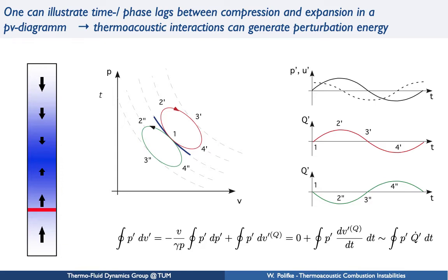And the blue line that you see here would correspond to isentropic compression and expansion that a volume of gas experiences if it is exposed to an acoustic wave. Only an acoustic wave, no heat release for the time being, right? For the blue line, it's only acoustics. Acoustics is isentropic, so you compress the gas, you expand the gas, but nothing interesting is happening.